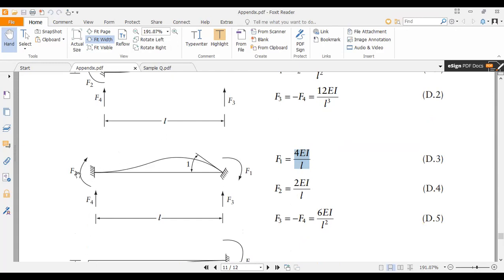So at the far end, you have induced bending moment due to this rotation. Let's call this theta x, then this point bending moment is 4EI theta x over L. And due to this theta x, it will have 2EI theta x over L here. That is the bending moment. The rotation is still zero. Only this support is rotated. These are the induced bending moments, right?